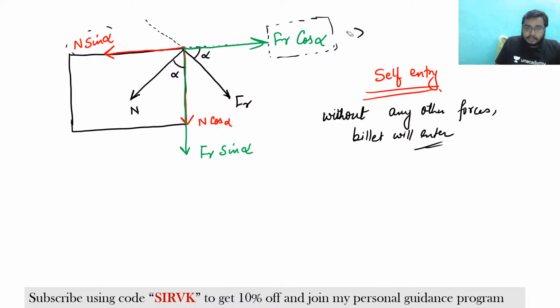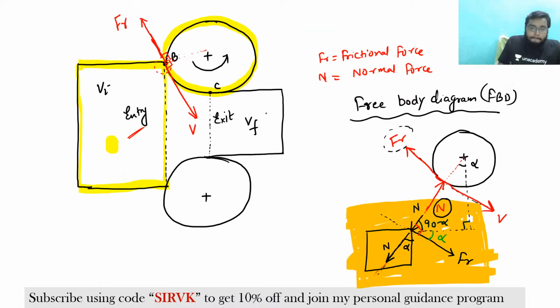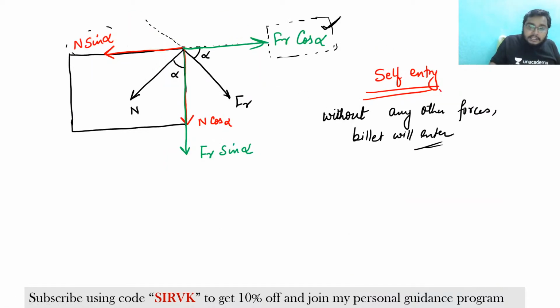See here, understand, my workpiece is moving in this direction, right? So if I want that my workpiece should move automatically on its own, so definitely this direction force should be greater than this. So can I write that Fr cos alpha should be greater than or equal to N sine alpha?